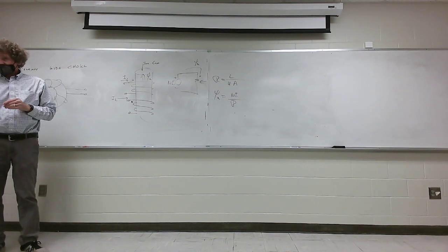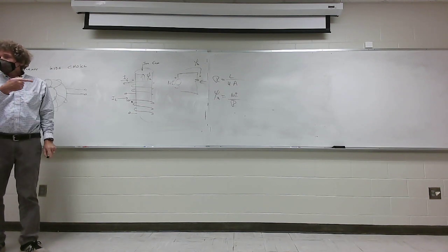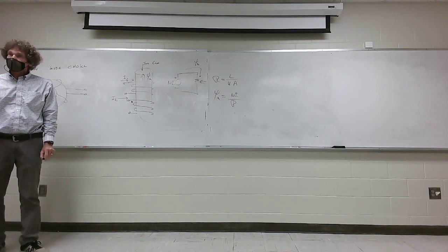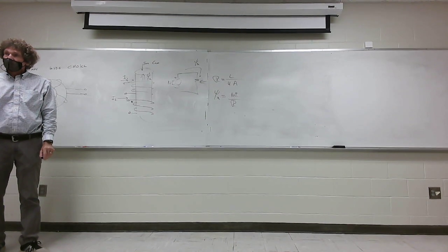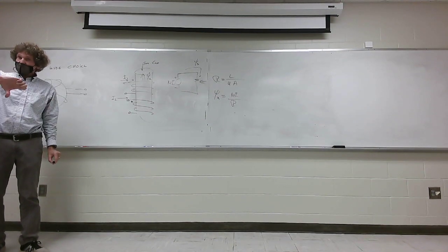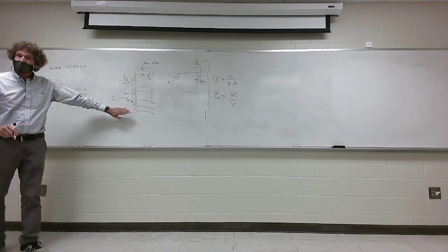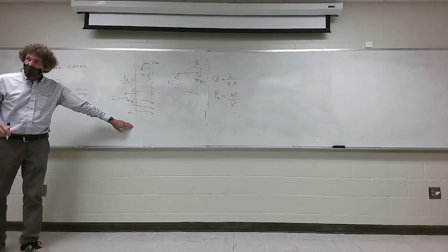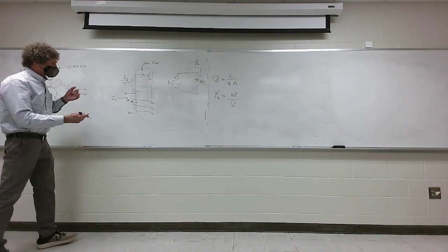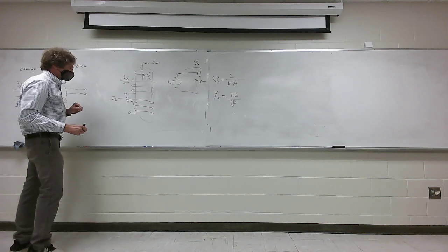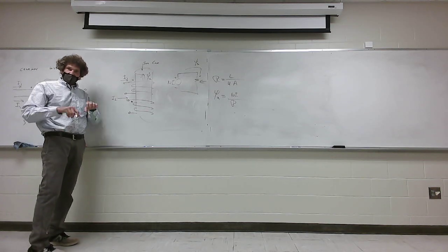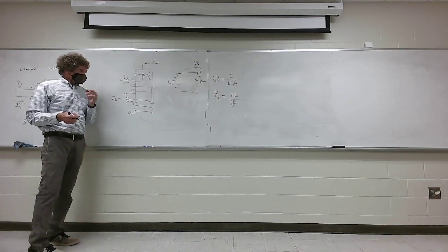I just guessed. Now, if the flux created by that second turn of wires is in the direction of the flux created by the first turn, then it's in the right place. But if it's not, if it's going the opposite way, you simply erase that dot and put it down to the opposite terminal. Y'all remember that? It's that simple. So anyway, that's basically what you got here, over there, and I'm just straightening out that core and showing you what you got.